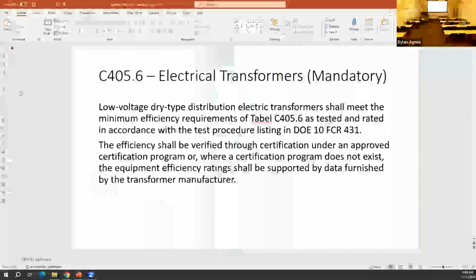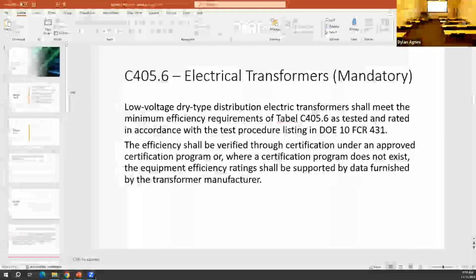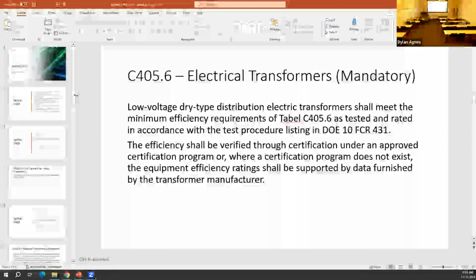Are they still requiring keypad operation in hotels, or hotel rooms? I'm not entirely sure, but you can use the key card access instead of having an occupancy sensor in the dwelling unit. Okay, and it will go off of that. I don't know if it's required, but that is one exemption you can use instead of installing an occupancy sensor or doing the time switch control delay.